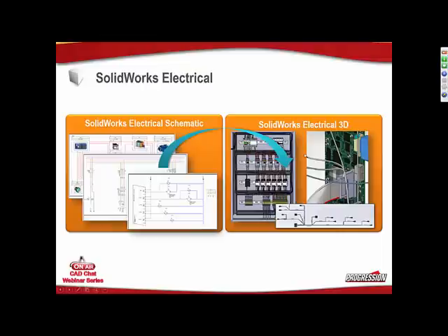And there's communication. There's actually a SQL database behind everything. The SQL database contains information about the schematics, including the symbols. The symbols will have components associated with them. The components will have SolidWorks models associated to them. So it communicates from the electrical side or the schematic side to the 3D side. And it's also bidirectional. So for example, if you delete a component in SolidWorks Electrical, that component is on a schematic, it will delete that component off the schematic. So it is bidirectional.